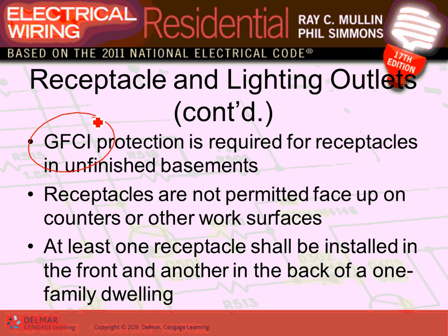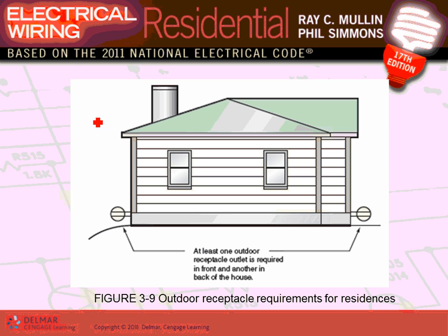Basement, garages, outside, unfinished basement, kitchen, and bathroom and sinks. If you have a bar sink in your basement, anything within 6 feet of the bar sink, you have to put on a GFCI. We talked about this. Here's how you have to bring it to the outside.